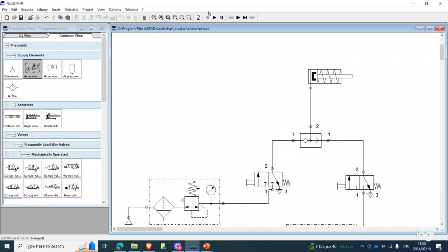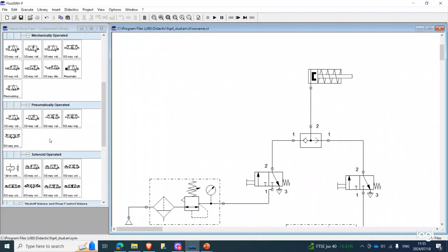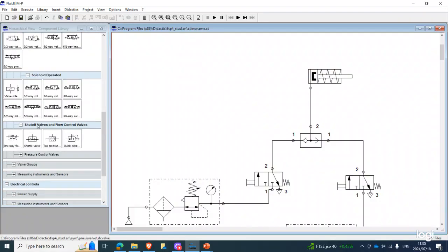So before I close off, I also want to introduce another gate related to the OR gate. So this is an AND gate, right? The difference between an AND and OR gate is that in an OR gate, we only need one of the push buttons to allow air into the circuit for the cylinder to advance.